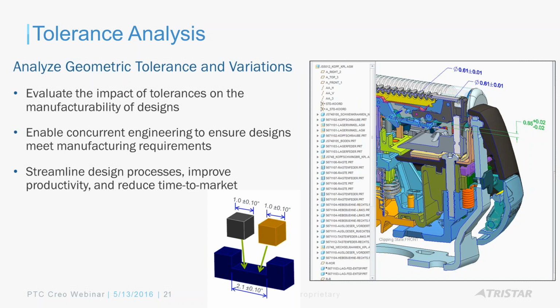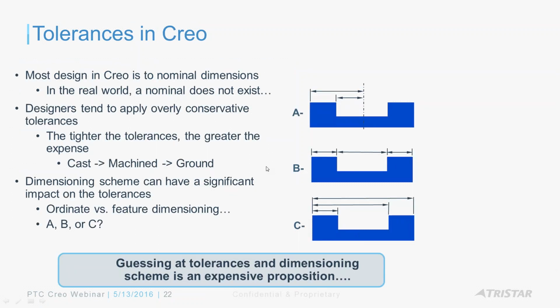So you're allowing for the variation, and as design engineers, or as mechanical engineers or designers, there's constantly a conflict of interest between engineering and manufacturing, right? Tighter tolerance means higher manufacturing costs, but for the engineer, the main thing is you always go for a tighter tolerance, and how am I able to tell manufacturing that, okay, we do need this sort of a tolerance stack-up, or a tight tolerance here, and my dimensioning scheme. A lot of things come into the picture when we talk about tolerances, right?